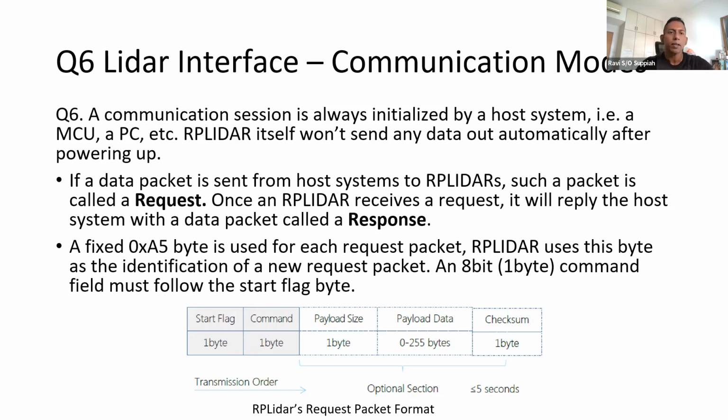All right, so for this LIDAR, as you have seen in the studio, we are making use of all the libraries already given to us, and here we are trying to understand the way in which it works. The LIDAR itself is very much a slave. It is waiting for the host to send it a request, and based on the request, it will reply. So there's always a request and there's always a response.